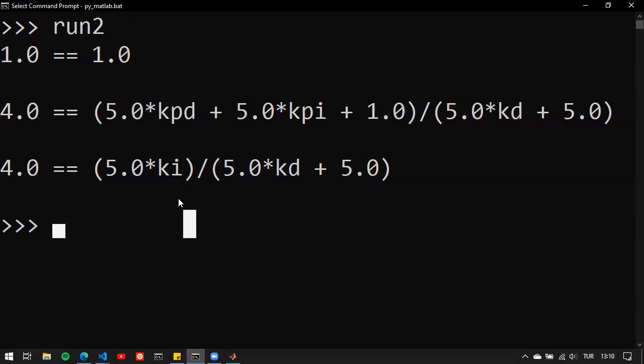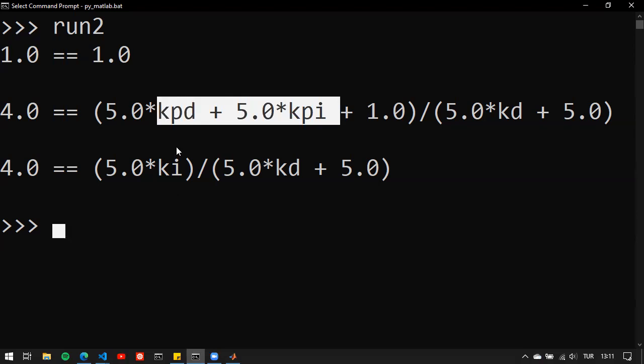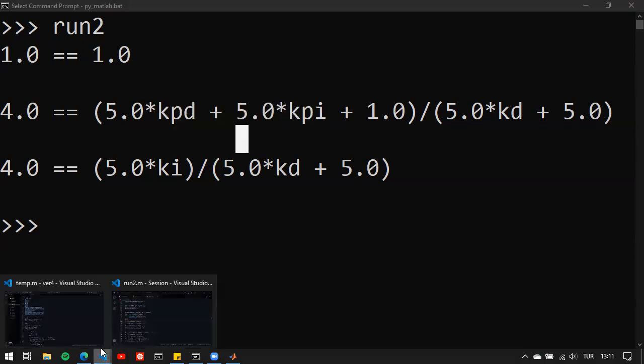So this is interesting because a lot of things have changed, but also nothing did really change. So yeah, the KD and KI values are the same. Therefore, you can use the same values from the PID controller, but you can decompose the proportional parts because their sum is equal to something now. So let's make a wise choice.